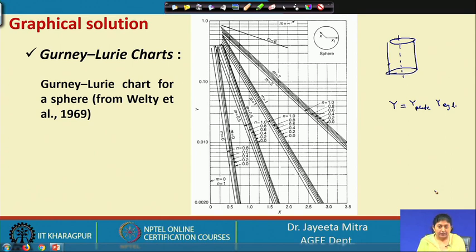we need to have the center point temperature because that is very important. The assurance that no contamination or microbial growth will be there is very important for preservation of food, and to ascertain that we need to maintain the center temperature at a set level, or perform the process in such a manner that the center temperature attains the sterilizing temperature.